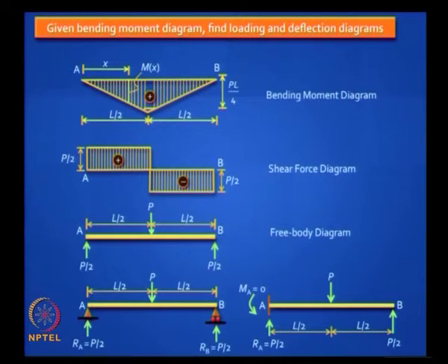So you can have multiple loading diagrams having the same free body diagram, and it is interesting to take this one step further and see how does the deflected shape change. For example, this would be the deflected shape for the simply supported beam, it will be symmetric. What would it be for the cantilever? Just rotated by theta. You are right. So you will find the deflected shape for the cantilever will be something like that, and these two deflected shapes are related.